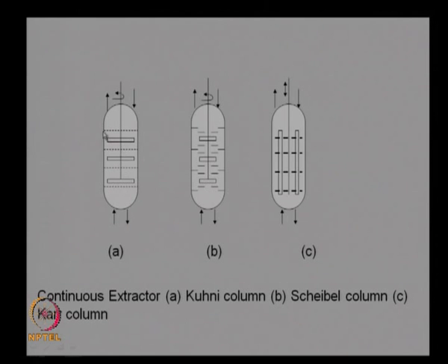So when you have many sieve plates and many blades, you are creating automatically several stages, where in each stage there is a mixing of the liquid and the heavies. So you can move the solvent from the bottom up or from the top down, depending upon the density of the solvent with respect to your fermentation broth.